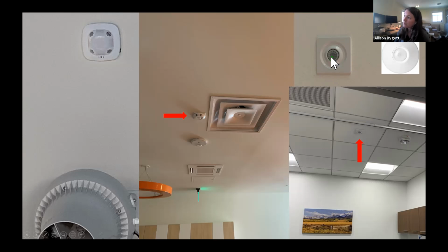And what I'm showing you is there's an indicator light in here. So I look to see that the occupancy sensor is physically located in the ceiling, but then I also check if it's powered. There's actually 2 LED lights in here. One of them is a low level LED light, and then there's a bright one. And as you move around the room, it flashes to show the movement. And I look to make sure that that's how the occupancy sensors are responding.